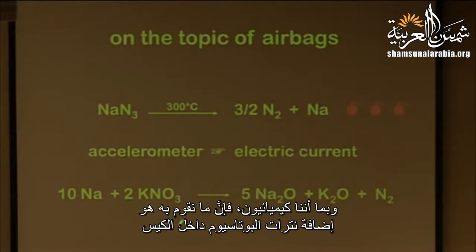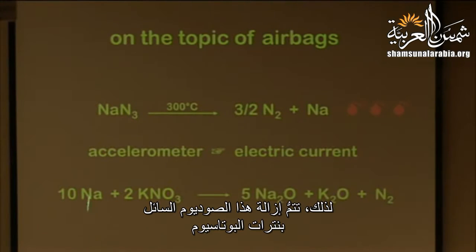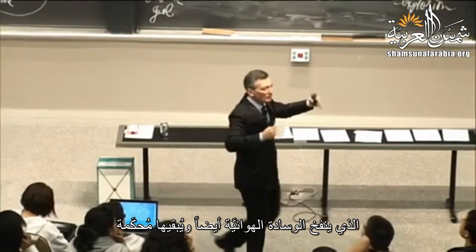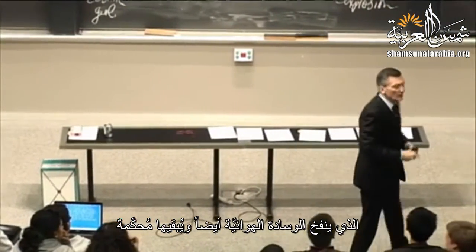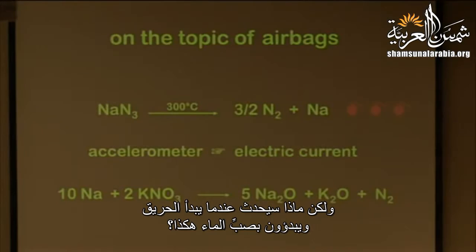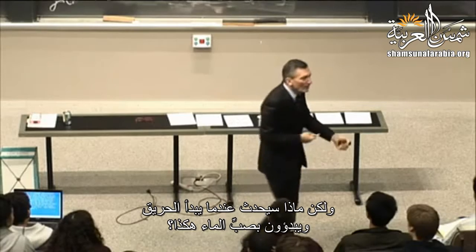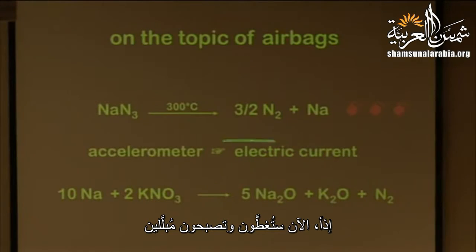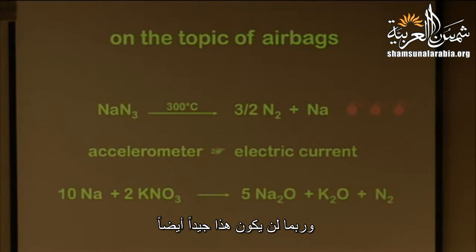So being chemists, what we do is we add potassium nitrate inside the bag as well, so that the sodium is mopped up with potassium nitrate, which converts it to sodium oxide, potassium oxide, and a little more nitrogen. Keep the bag nice and firm, all right? But now what happens when the fighters show up and they start pouring water on it? This turns into caustic. So now you're going to get covered in wet lye. So that's probably not too good either.